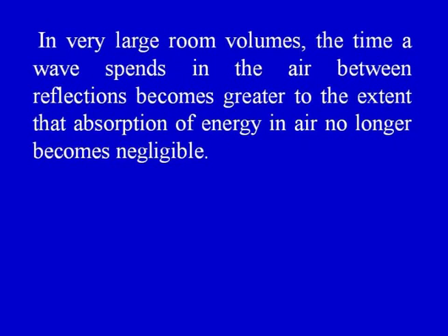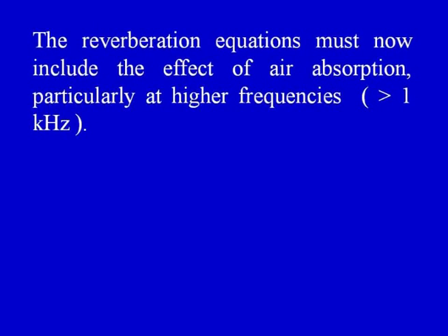In very large volume, big halls, the time the wave spends in the air between reflections becomes greater to the extent that absorption of energy in air no longer becomes negligible. The reverberation equation must now include the effect of air absorption, particularly at high frequencies higher than 1 kilohertz.